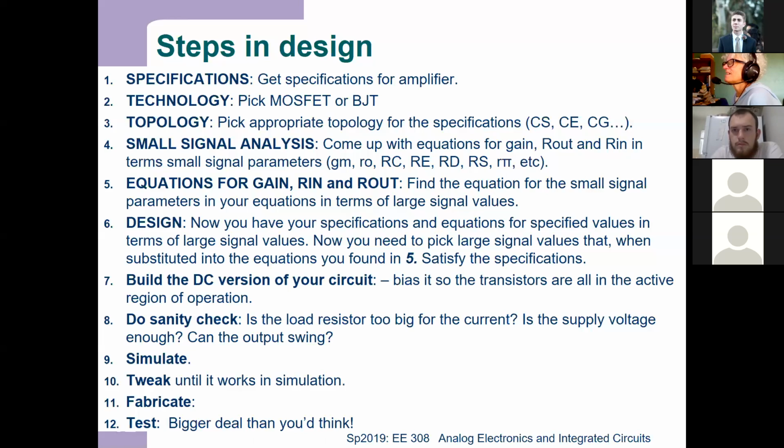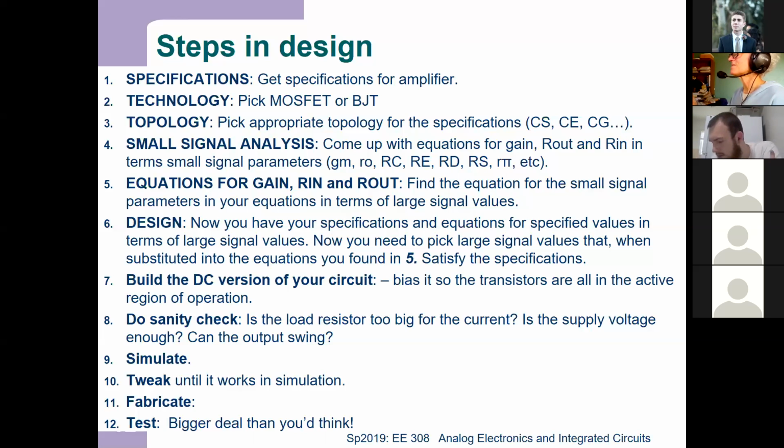There's 3 different types of amplifiers: common source or common emitter, common base or common gate, and then common collector or common drain. So if somebody says, oh, you need a gain, which one do you get rid of? So which one has the lowest gain? Common collector. Yeah, the common base has good gain, so that would still be in the running.